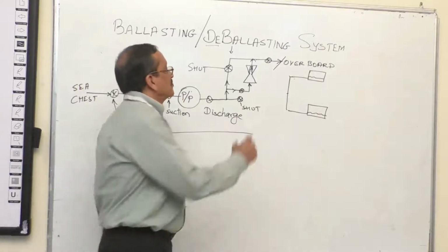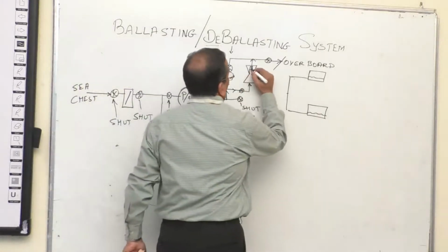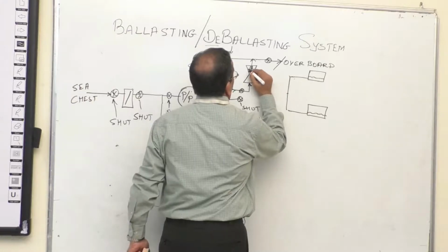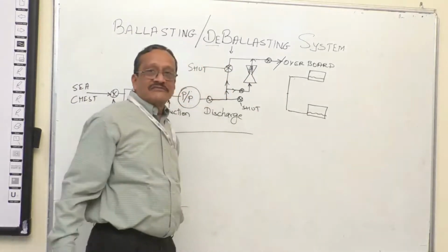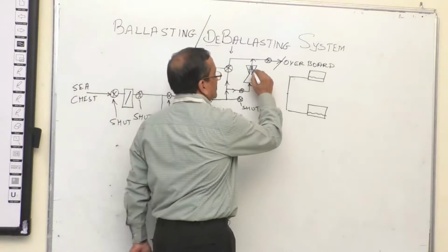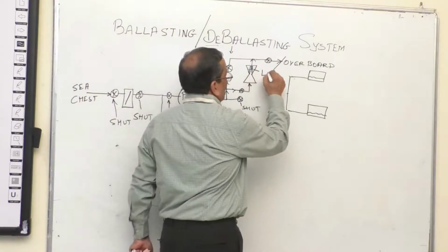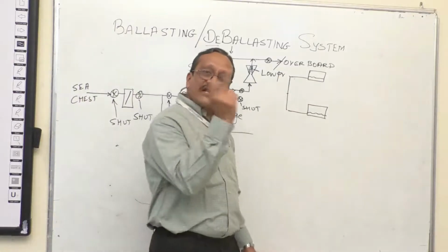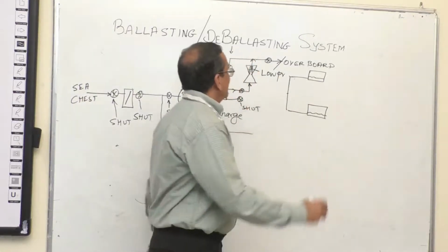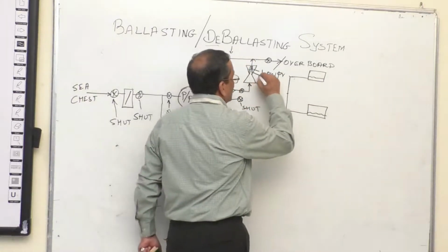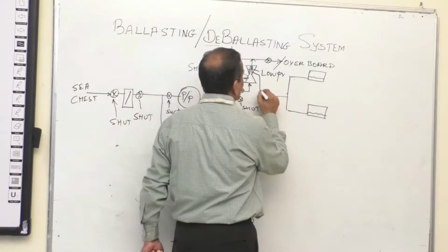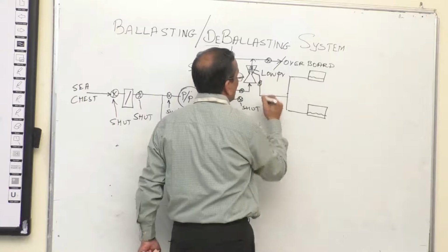Now if you can understand this, when it is passing through this point over here, what really happens is that when it is moving at a good force, it creates a vacuum in the annular space of the nozzle. So when there is a low pressure being generated in these annular spaces, this space is what is connected to our tanks. So I have a valve.